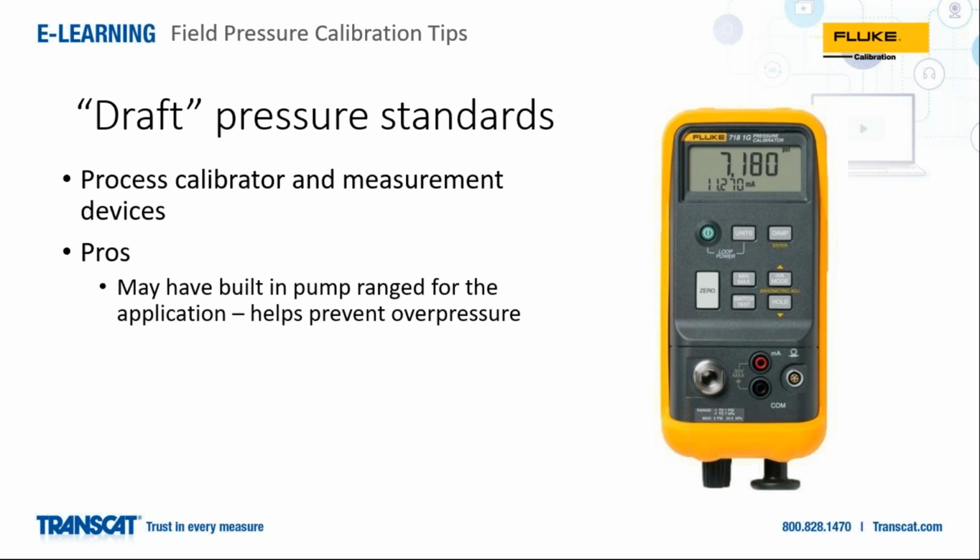The other thing is that the pressure sensors themselves are different between the different calibrators, and the pressure sensors are not just an off-the-shelf drop-in item. The pressure sensors themselves are characterized for the performance in these systems. I've seen the results of this firsthand. If you were to do something like, hey, I blew the pressure sensor, but I'm a smart guy, I can take this apart, replace the sensor, and fix it, what you end up with, instead of a linearized sensor that reads in a linear fashion over the range, is this kind of parabolic curve.